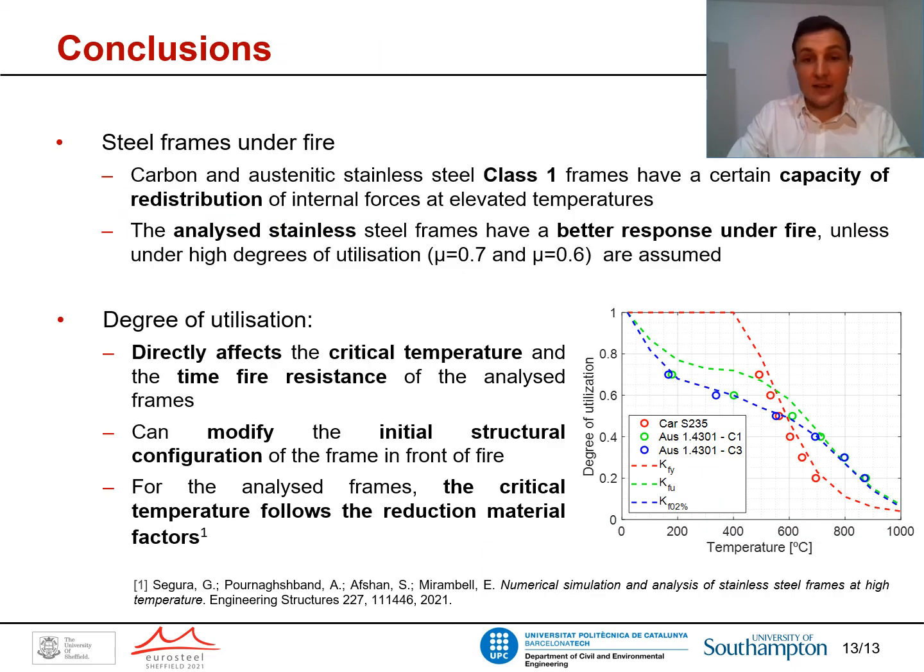Finally, this slide shows the main conclusions of this presentation. First of all, both carbon and stainless steel Class 1 frames show a great capacity of redistribution of internal forces at elevated temperatures. Moreover, the analyzed stainless steel frames seem to have a better response under fire, unless a very high degree of utilization is considered.